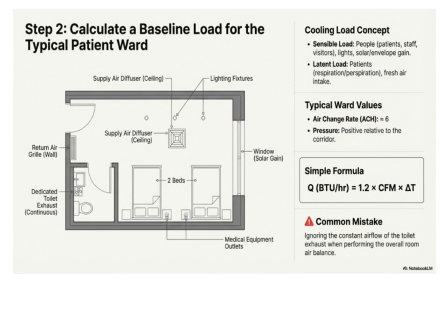And don't forget, when we're balancing the air, the exhaust from toilets must be included. Proper air balance ensures good indoor air quality and helps maintain the right pressure relationships throughout the building. All these factors are interconnected and crucial for designing an efficient and effective cooling and ventilation system.